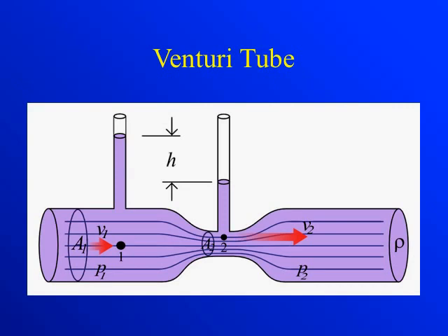The tubes of still water are being pressed up by the pressure at 1 and 2. But the pressure at 2 is less, so there's less fluid to be pressed up with lower pressure at 2. So the heights of the tubes record the pressures. The heights of the tubes are acting as gauge pressures, gauging the difference in pressure between P2 and atmosphere. And the vertical tube is gauging the difference in pressure between P1 and atmospheric pressure.